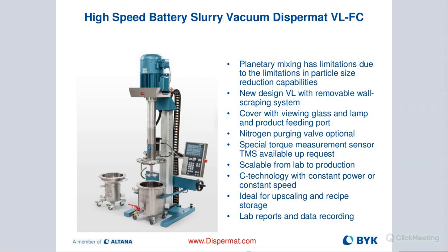A lot of safety features also. Just want to mention all these units are intrinsically safe. We have a number of safety features built in. The container clamping system. So basically that wheel on the right side there, that allows you to tighten the container. If the container is not perfectly centered or loose, then the machine will indicate that on the display. It will not start up unless the container is fully secured. We also have what we call the working area threshold setting, H1, H2. So we have an upper and a lower limit inside of our container.